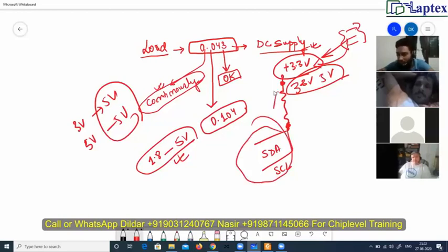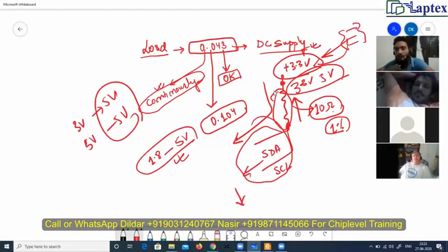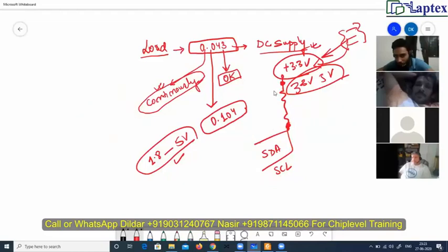Did you check this resistor value, how much it was coming? I will check it tomorrow. You need to check this. This is a 10 ohm resistor, a very sensitive value, and it's a 1% tolerance. We'll discuss all these things when we come to the charging section. If its value increases, then the current injected into the SDA and SCL will be low, and the IO will not get all the information of the battery, and your plugged in not charging message will come when you see in the battery. We'll come to those problems later, so we'll stick to this problem now.